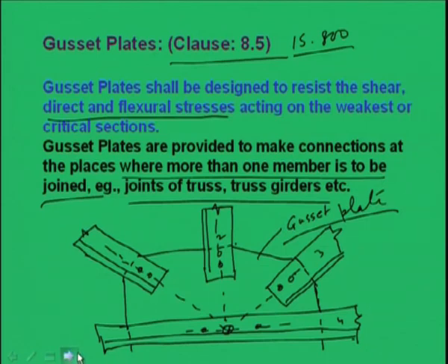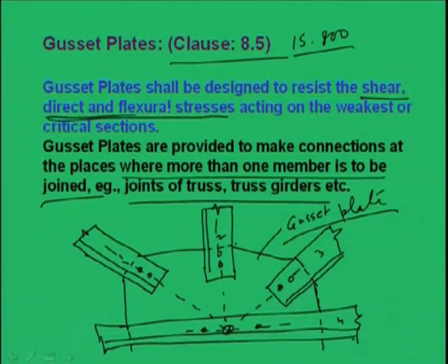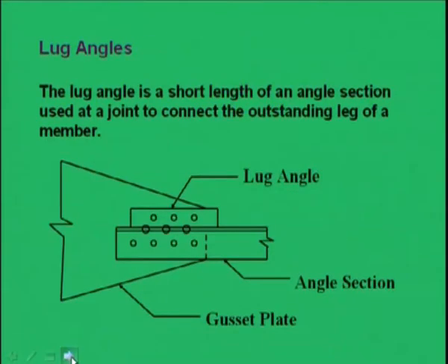Regarding the gusset plate, I will not discuss much because we are already familiar with this term, and whenever we go for designing such types of connections we generally use gusset plates. And we have to design the gusset plate in such a way that it should be able to resist shear, direct and flexural stresses. So all these things we have to keep in mind.